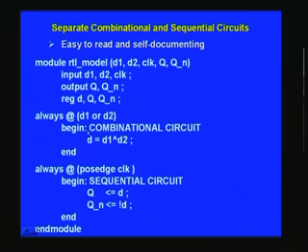And you notice that we have given a name here after begin. You are already familiar with begin and end. What has come as extra here is just a colon here and a combinational circuit name. That means to say whatever block that you have here, you can give a specific name and perhaps call it later on when the need arises. Or you can just, for improving the readability, have this.